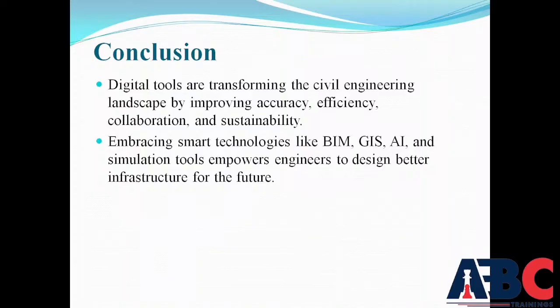So by using new technologies and software like AutoCAD, Civil 3D, Revit, SketchUp, and Navisworks, we can detect our clashes. Suppose we are building a structure on our site and you get some clashes, like your beam or your duct is going to be combined, or electrical piping or any other thing is going to be combined with each other. So clashes begin there. With new technology like Navisworks, you can detect clashes before the structure is constructed on site.